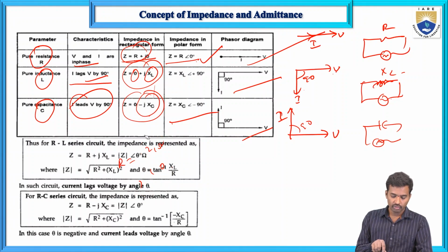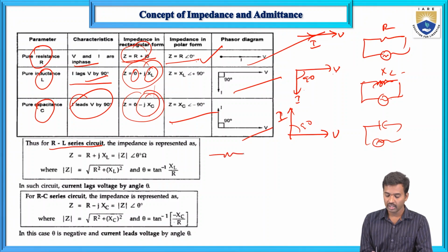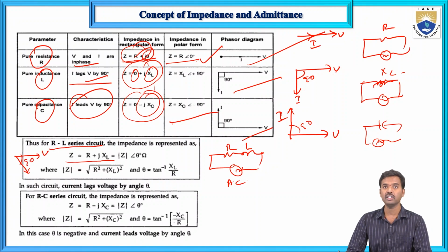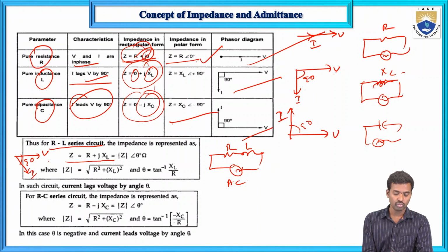So now what about the formulas for RLC circuits, the RL circuit? So R and L are connected in series, and the entire circuit is connected across the AC supply. So for that case, Z equals R plus JX, where there is an inductor. For that case, not exactly 90 degrees. There may be a voltage and current difference that is not exactly 90 degrees. So current lags voltage by some angle phi, that angle phi or theta. In the previous case, there may be a 0 angle.